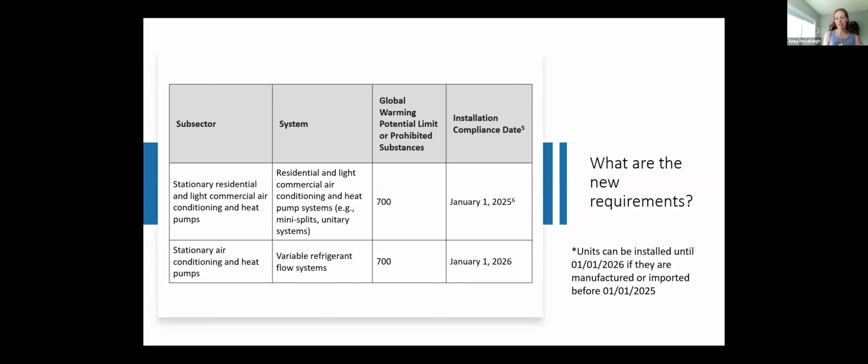But if you have a fire protected shaft, even if it is a 2 hour rated shaft, you are still going to have to provide this protective shield. I can't remember what the rating is that you can go up to where you don't have to provide the shield, but if you can puncture through that wall and get to the refrigerant lines, you have to provide the shield.